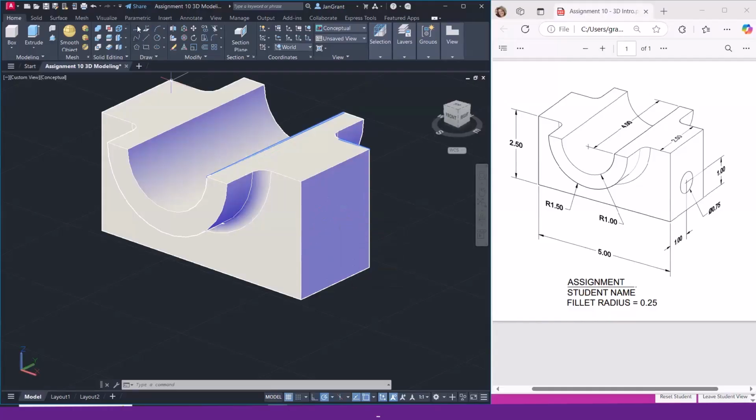So let's do that. Start the line command, just regular 2D geometry line. Make sure that this surface is highlighted like a blue, and then click the midpoint of the bottom edge right there. Pull your mouse straight up and type in 1 and enter, and then enter again. See what it did was it just drew a line that was from the midpoint of this bottom edge up 1.